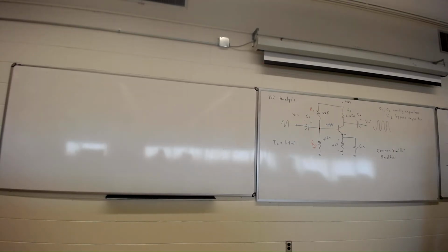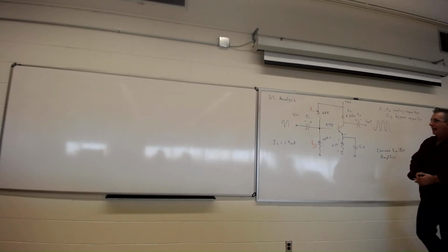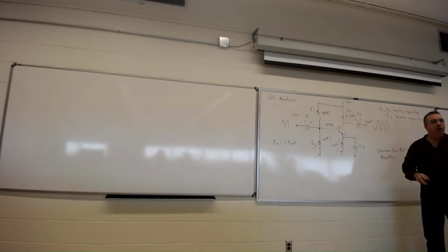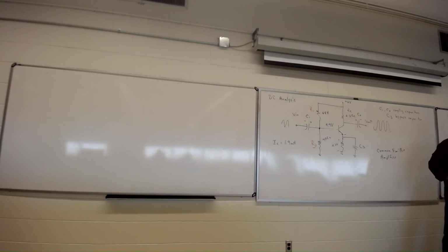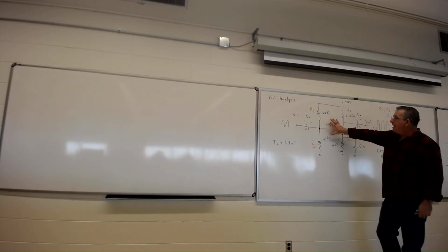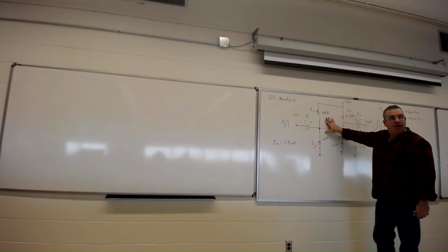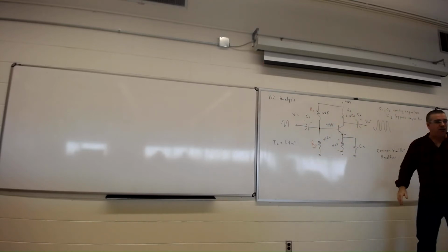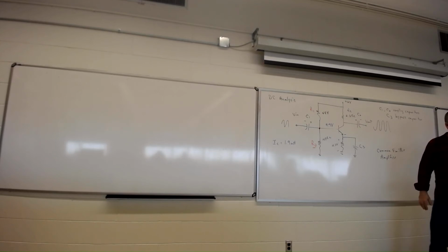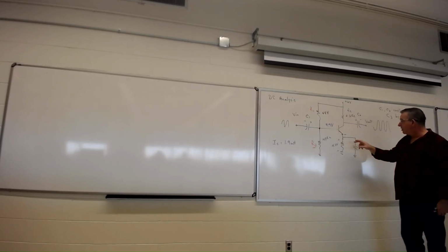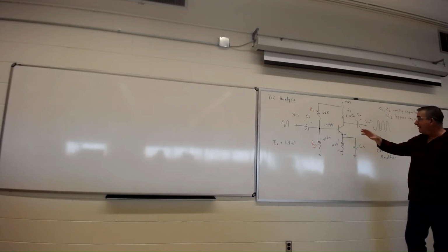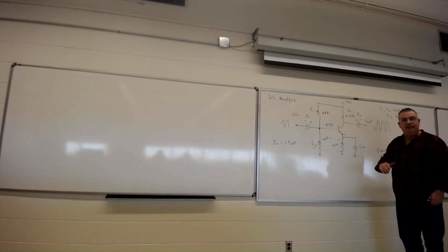Now, the reason the capacitors are important there is that capacitors only let AC signal go through. Capacitors block DC. So whenever DC biasing is going on inside the amplifier, it's not capable of leaking out to the next stages, all right? It stays inside here because the capacitors block the DC from going through. The capacitors let AC go through, but they don't let DC go through.